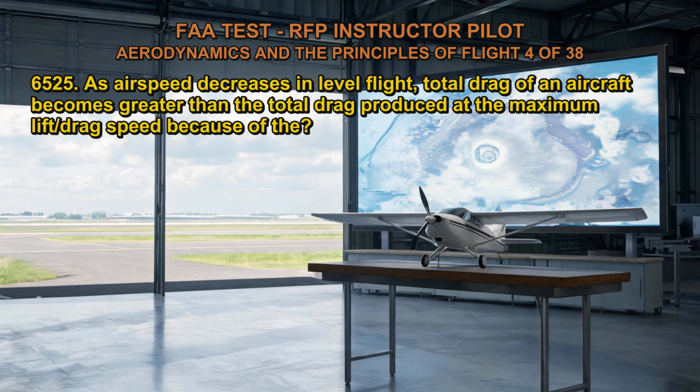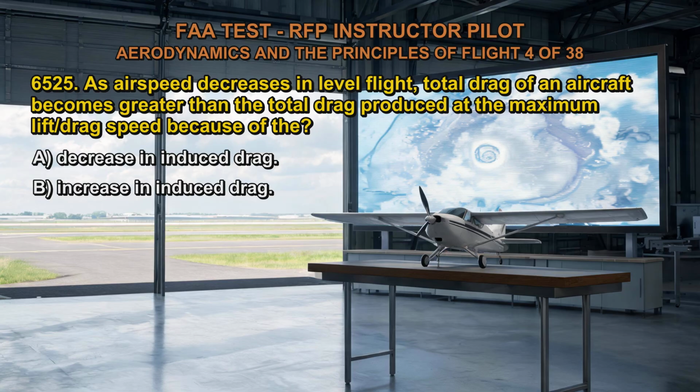6525. As airspeed decreases in level flight, total drag of an aircraft becomes greater than the total drag produced at the maximum lift/drag speed because of the A. Decrease in induced drag. B. Increase in induced drag. C. Increase in parasite drag.